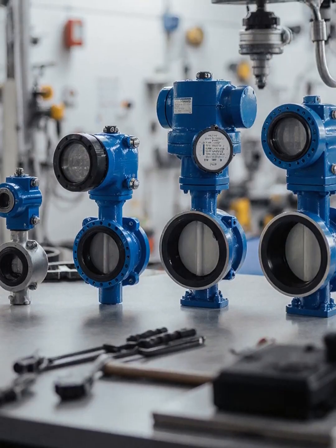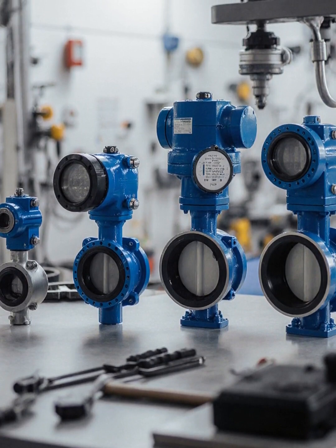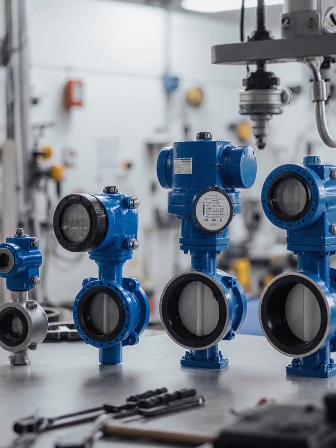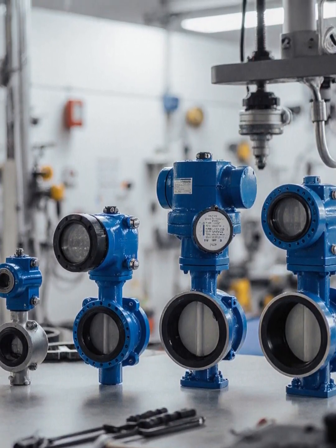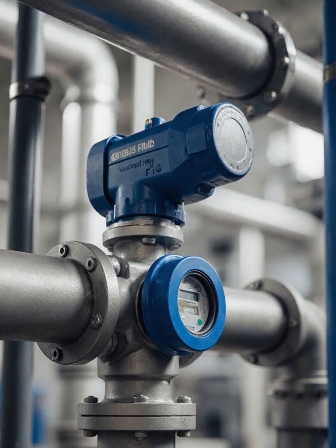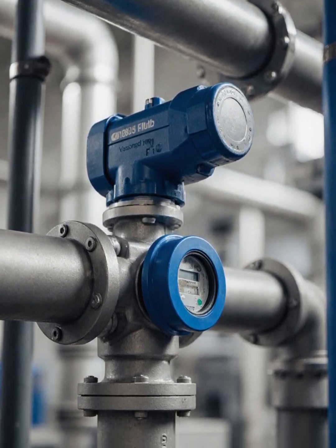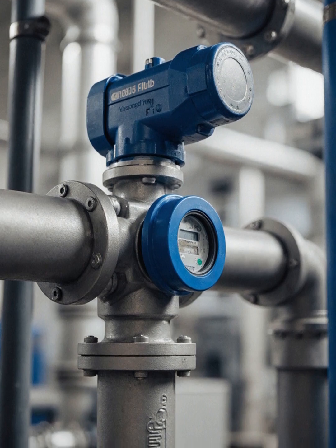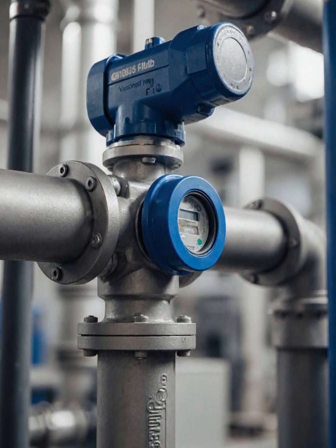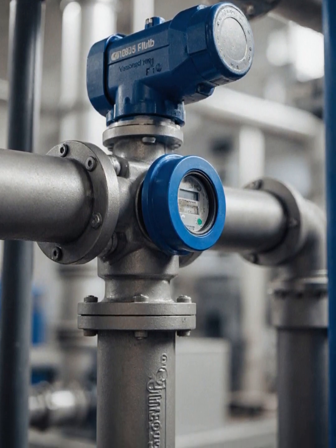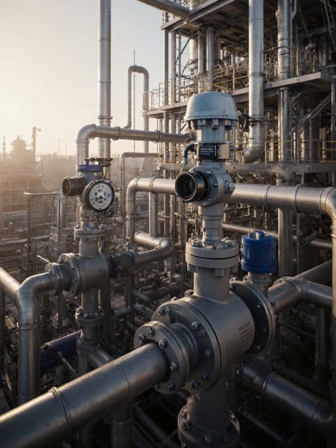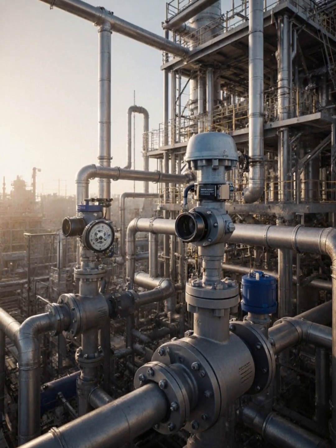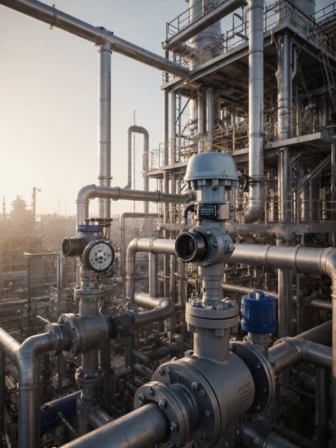The fundamental types of flow meters are categorized by what they measure, volume or mass, and their operating principle, including volumetric, positive displacement, turbine, vortex, ultrasonic, magnetic, for volume, and mass flow, Coriolis, thermal, for direct mass measurement, plus differential pressure, orifice, venturi, and velocity, paddle wheel types, all designed for different fluids, conditions, and accuracy needs in industrial applications.